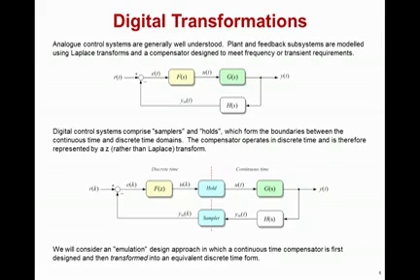In the digital domain, we add two components. First, a hold, so this would be the PWM module that's generating the signals that would then be output on the plant, which you see here as G of S, and the sampler, which is our analog to digital converter, A to D, that we have on chip to measure signals from the plant and convert them into digital values that we can use in the discrete time domain you see on the left-hand side of the screen.